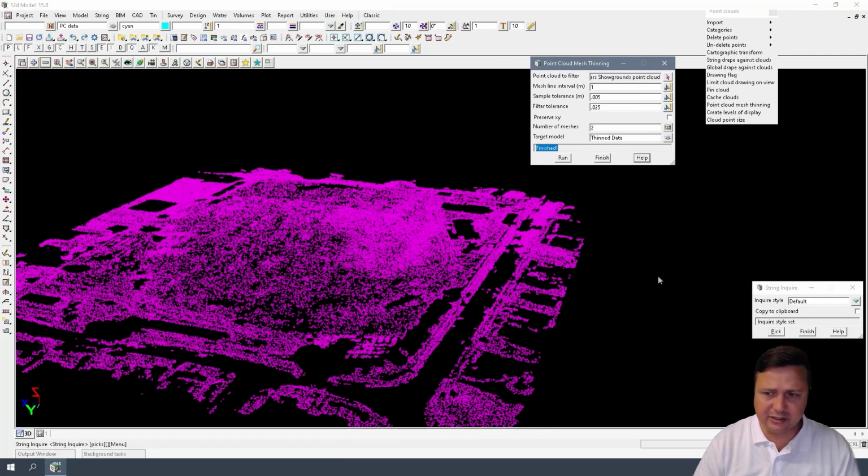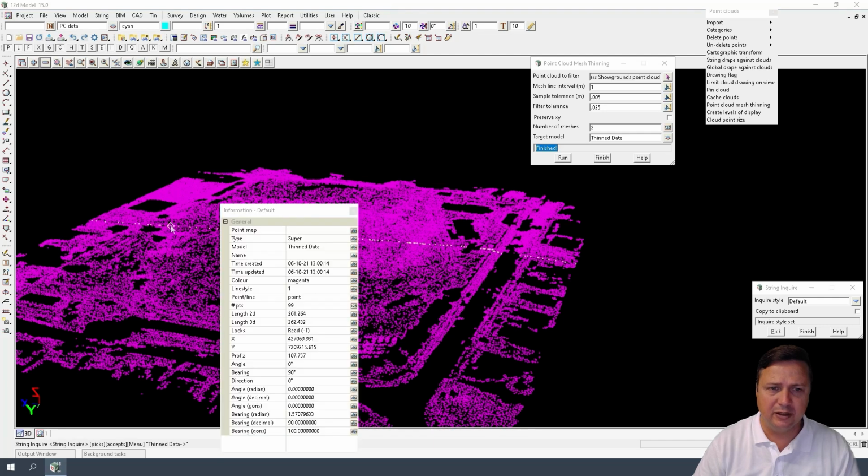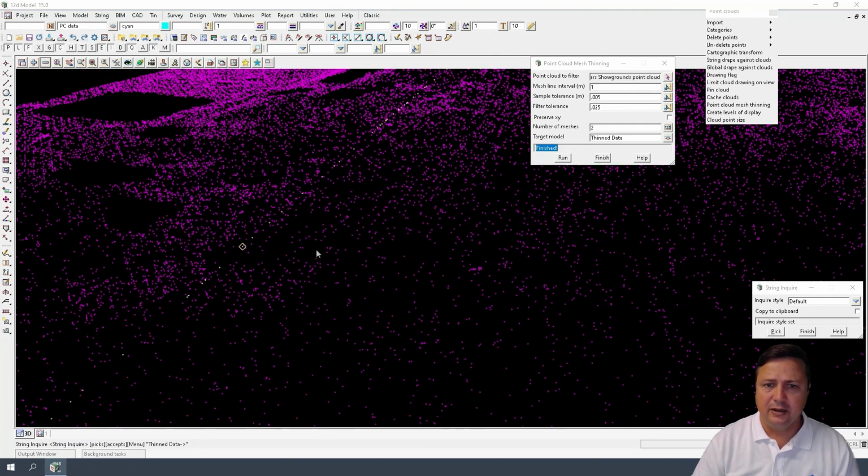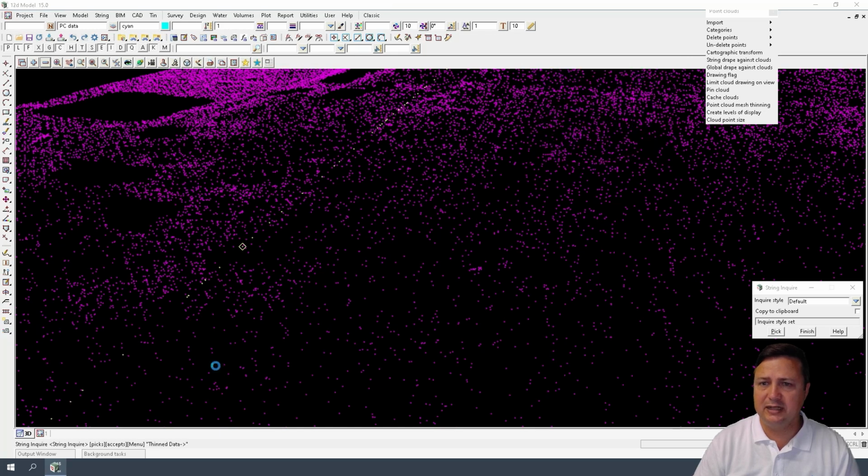And you will notice that when I pick on a line, it's in that grid fashion, so you can see them all highlighting along the screen. So they're still all in their original grids that it created. Okay, so let's tin this and we can have a look at manipulating this data a little bit more.